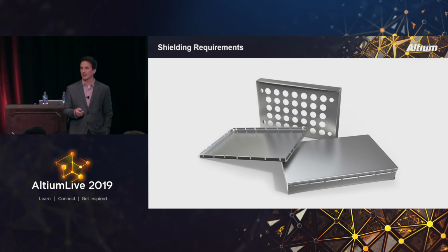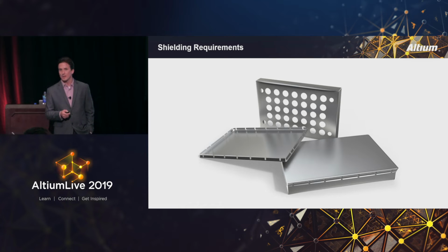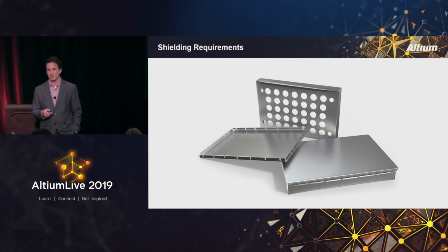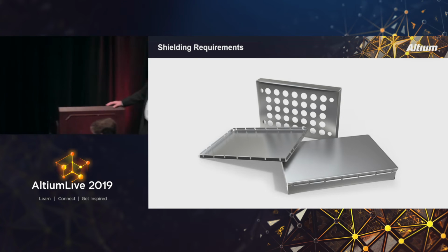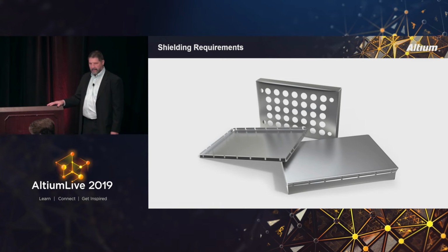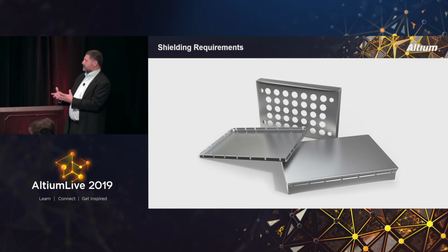this is, again, another thing that you need to have a discussion about early in the design. And not doing this just to solve a problem at the end, and having a discussion about whether you're going to include shielding or not. So the cost of shields is generally going to be determined by the complexity of the operations and the cost of the tooling. So here in the lower part, you see like a stake that has a cover. The top one looks to me like it's a single shell that's been manufactured from a stamping. So the cost of the shields is going to be greatly determined by that.